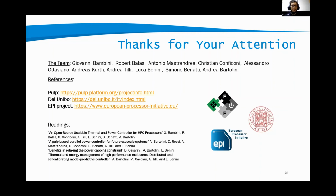Regarding the simulation, we have the state space with the matrices that take into account this close vicinity and interaction between core temperatures. So in the simulation, we took that into account. Regarding the real system, we cannot be completely sure. We can only read the sensor temperature, but that's what we have a margin for. So we have a margin in the controller, so we can still avoid reaching the thermal breakdown or the thermal limit of the core.